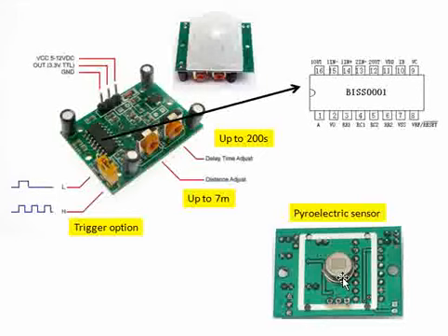So ultimately we can say that it's the temperature change, right? But how does it work with humans, how is it detecting? Humans emit infrared radiation from their body. When a human passes by a particular area, for example if a human walks by, there will be a temperature change around those surroundings. That is what this pyroelectric sensor is going to sense and develop voltage.